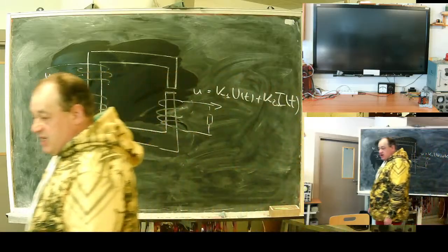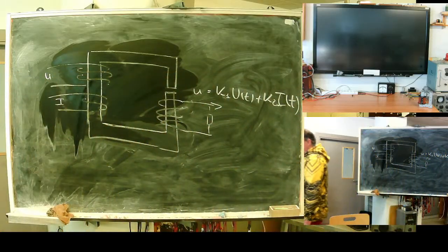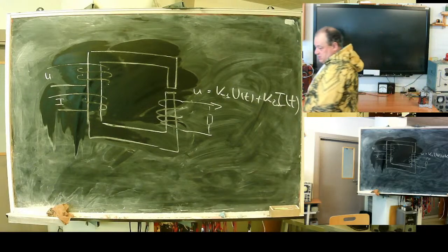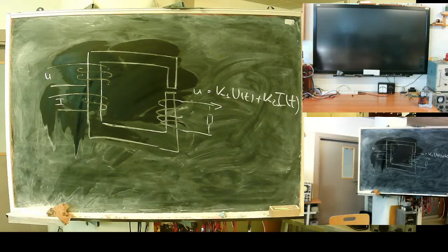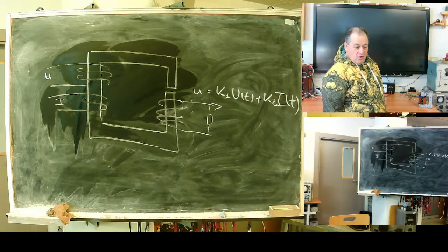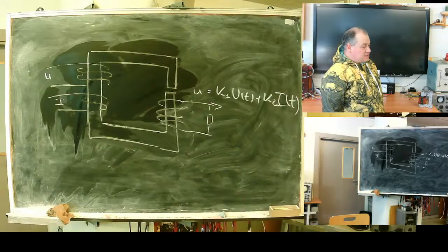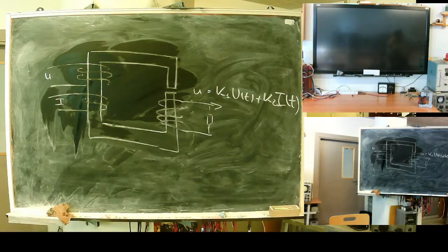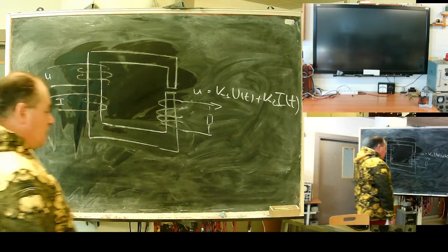For early generations of digital processing, some mass operations were performed in analog form with the help of what are called transreactors, linearized transformers. Nowadays it should be considered obsolete, but if you need to recommission an old device, be careful, you may find this object.